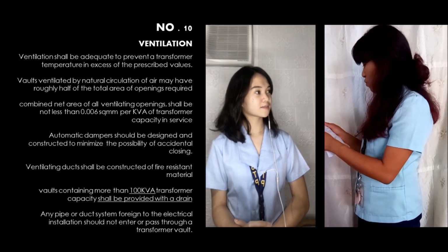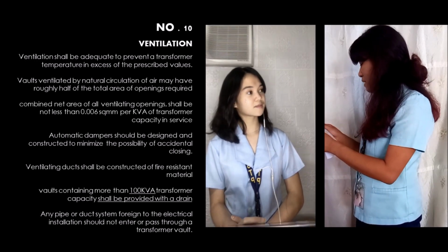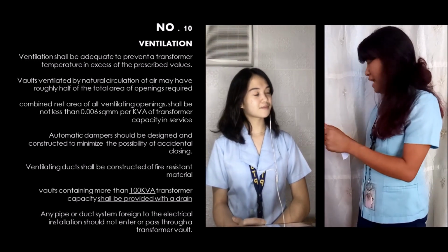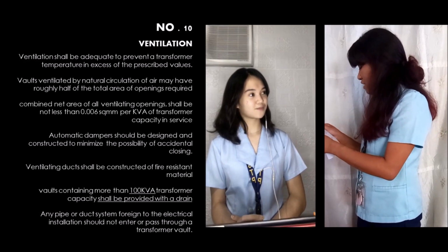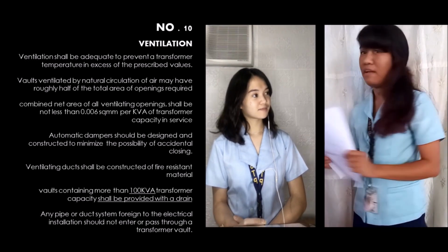Vaults containing more than 100 kVA transformer capacity shall be provided with a drain. Any pipe or duct system foreign to the electrical installation should not enter or pass through the transformer vault.